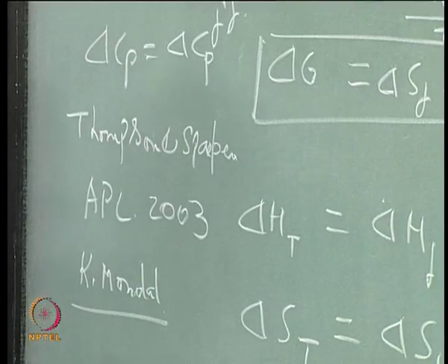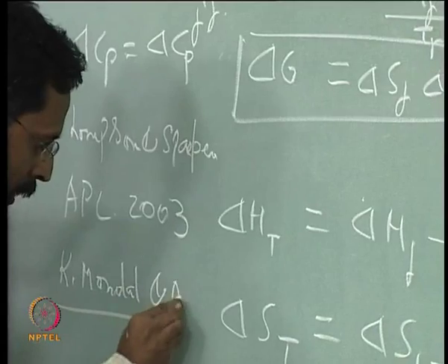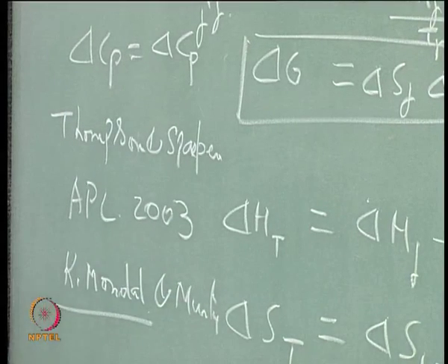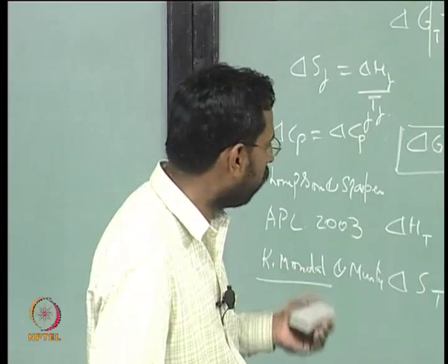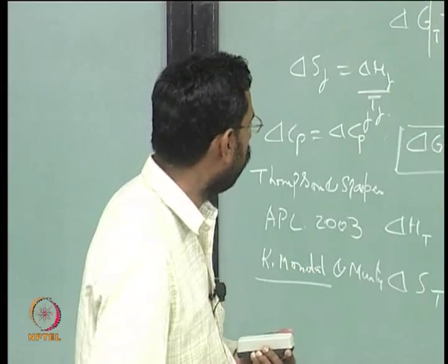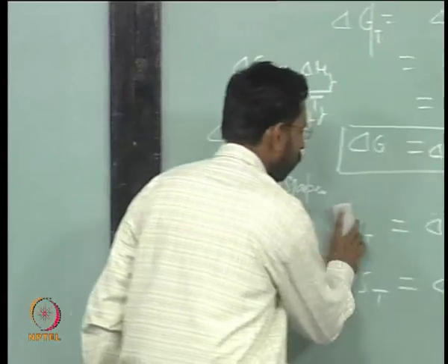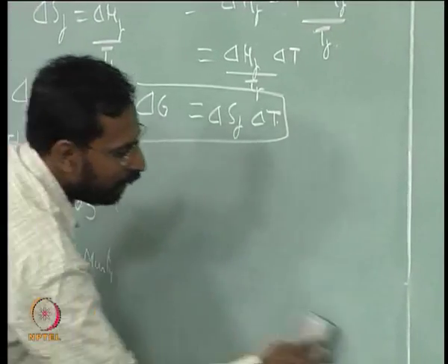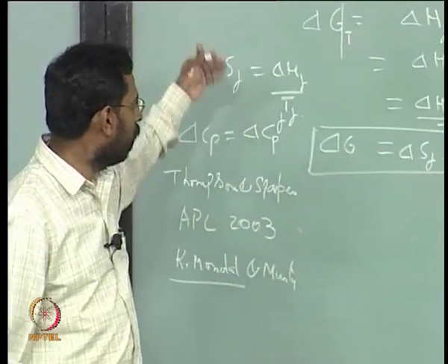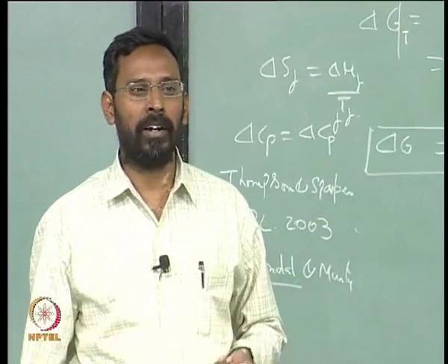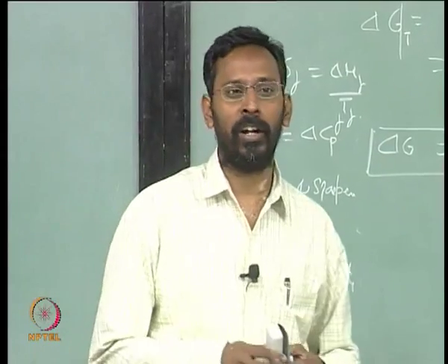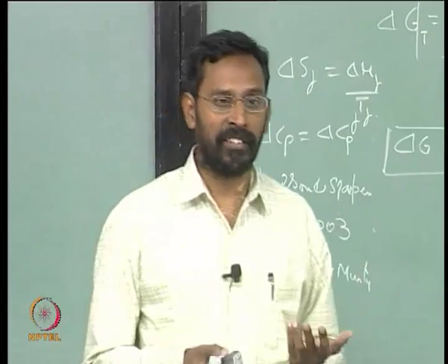You can see Mondal and Murthy, where we have tried to do certain other ways of doing the same thing. I do not want to go deeper unless you are really serious about it, to find an expression which would fit a variety of liquids, because most of the assumptions that people have made each have certain limitations. It would fit for binary liquids, but it would not fit for ternary and quaternary, because now we are talking about bulk metallic glasses.